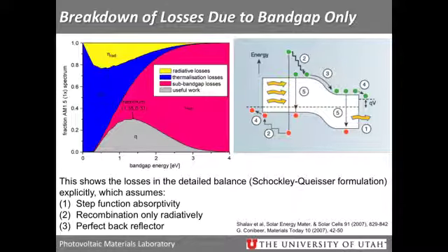Okay, so this diagram on the right diagrams some of these issues. Number 1 is light passing right through, so sub-band gap. 2 is thermalization of carriers. 3 would be a loss in voltage as you pass through the electric field in the junction. 4 is your contact resistance. Depending on how your work function and Fermi level line up at your contacts, you may lose available voltage there. And so these are all efficiency losses due to simple device physics as you're building your cell architecture.